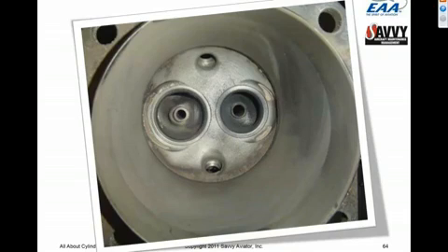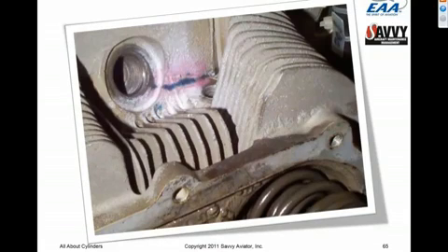Here's the most common place that we see cracks, and this is actually off of a cylinder on my airplane. The most common place we see cylinder head cracks is between the top spark plug hole and the fuel injector boss. These cracks are not particularly serious because once the crack goes from the spark plug hole to the fuel injector boss, it's basically stop drilled at both ends and isn't likely to go any further. The funny colors on there are dye penetrant.